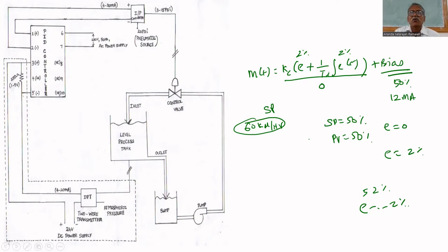So the function of the PID controller is not opening to 50%. It will adjust about 50%. You understand the difference? That only it can do. If any change is there, for that only it can control. One reason is non-linearity. I cannot talk about that; it is a very big topic. We'll see later. Because of that non-linearity, you cannot find a linear relation for that bias.